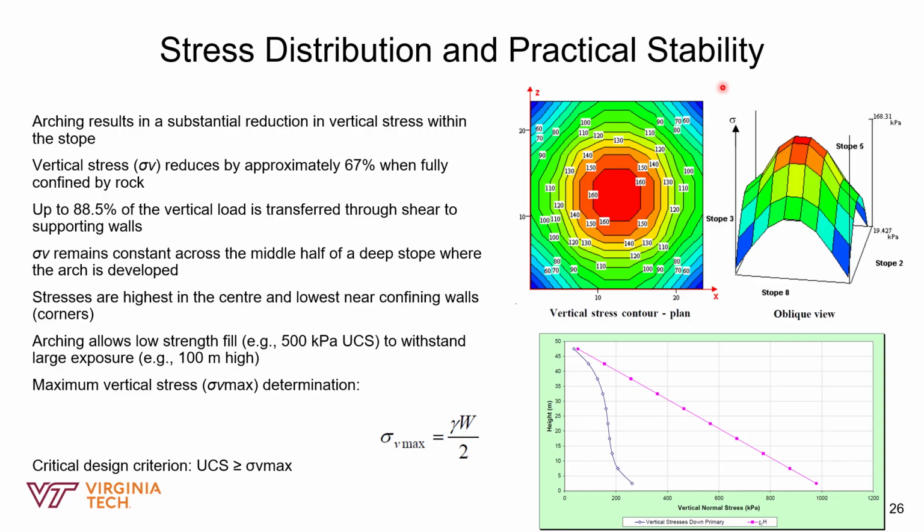The major trend is that the stress is highest in the center of the stope, reaching around 160 kPa, and lowest near the confining walls and especially in the corners, where the stresses are around 60 to 70 kPa.